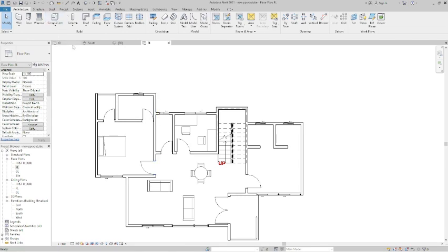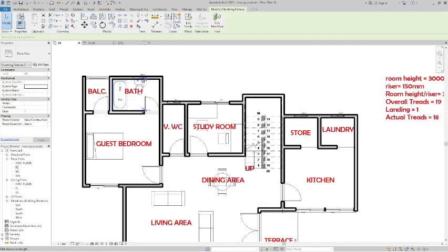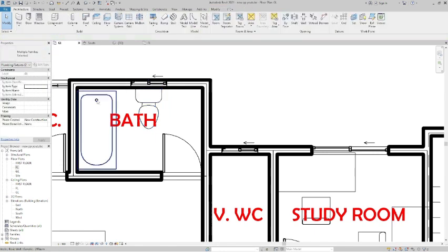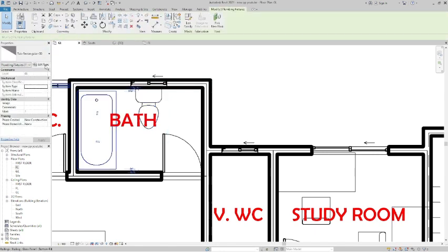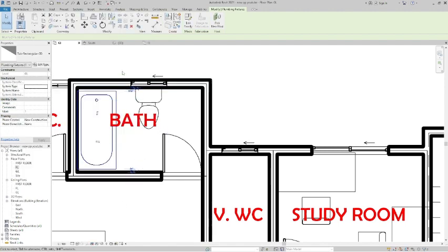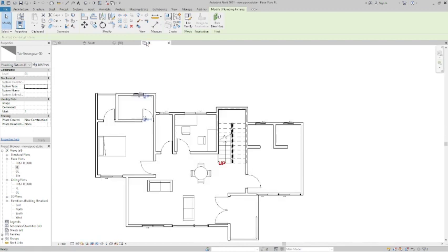So meaning you have to select this, select this one. Let me do it one by one. So select this, go to edit, default elevation. So I'll type in 300 and change it to wireframe.